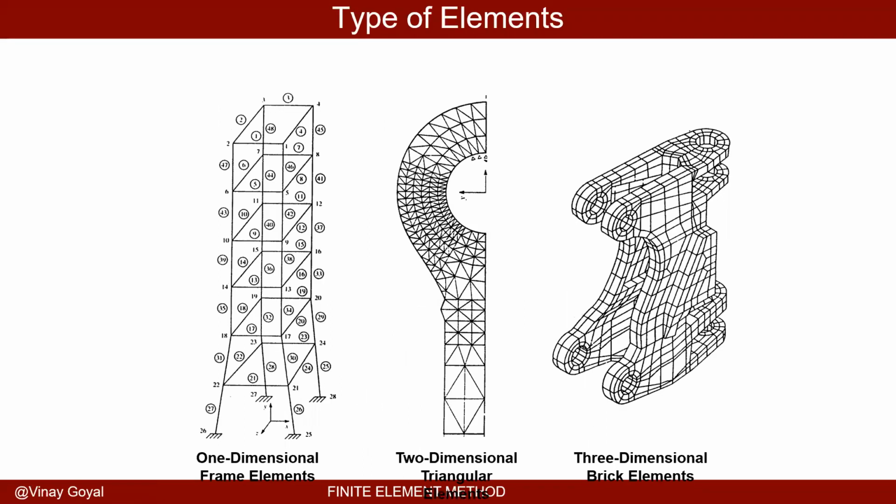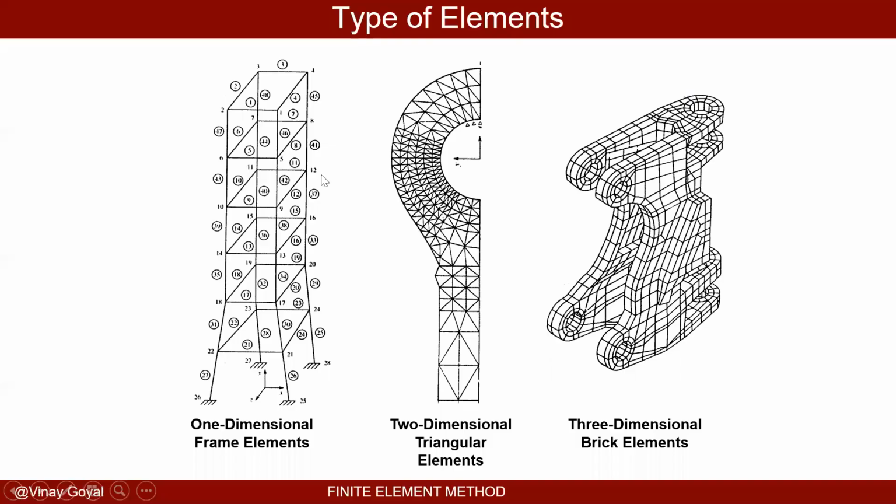Here, what I'm showing you is the different comparisons of a one-dimensional element. These are just beams, and that makes sense because these are frames, and so these frames can help react to loads in a very, very effective manner. But using three-dimensional elements for these beams will be very ineffective. There's no point in doing that.